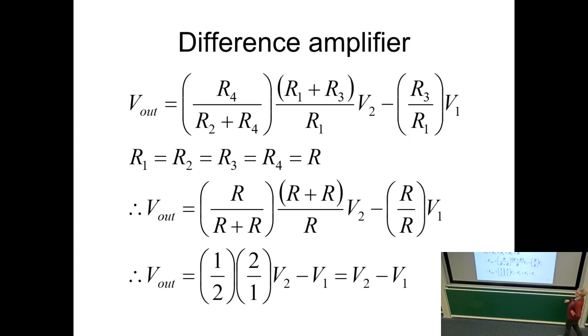And one thing that we've done throughout this lecture is we haven't cared about what's in the op amp at all. There's a whole bunch of transistors in that op amp doing God knows what, and we don't care about it as long as we can say that A is very large and apply the virtual earth theorem. We've done adders and subtractors, we've done them in half an hour, and it's straightforward if you do a bit of practice.